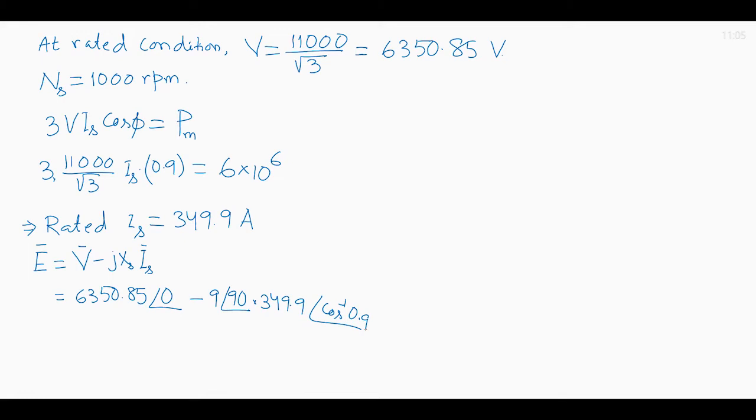Computing this, the induced EMF at rated condition comes as 8227 at an angle of minus 20.15 degree. So, these are all rated conditions.